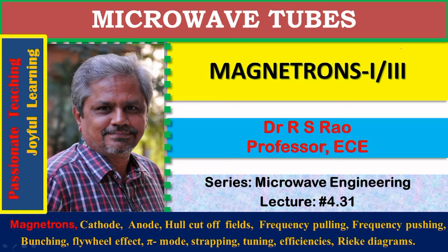These magnetrons are basically diodes. They have two electrodes, one cathode and one anode. In cylindrical magnetrons, the cathode is in the shape of a cylindrical rod. Inside this cylindrical rod, there exist heater coils. When the coils are connected to a power supply, they generate heat, raising the temperature of the cathode. It leads to emission of electrons from the surface of the cathode.